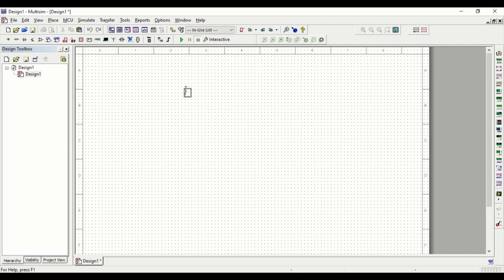And as that happens, you could also call out the text box. I'm writing here, this is a demo of Multisim or a demo with Multisim. Basically, you just go to place and then text is the option that I selected. There's also a shortcut just like any other software that you can actually use for this. But for example, that's one thing you could do. Place text. Sometimes you will have to document your designs with labels and such things.